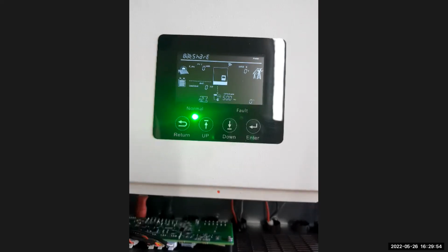I see I have a question here. Let's quickly answer the question before we go on. If you have a 200 amp hour battery and 2 inverters, do you set each inverter as 200 amp hours or 100 each? You only have to do the battery settings on the master inverter, then it will relay the settings to the slave inverter. So it's not necessary. You put in the master inverter as a 200 amp hour battery system, and then it will be fine. So you don't have to put 100, 100. It's a 200 amp hour bank that the 2 inverters are sharing.